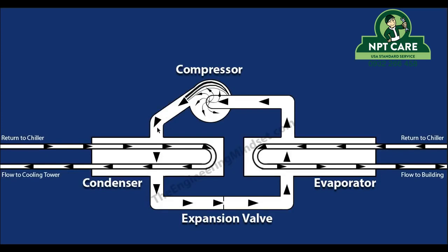The refrigerant comes in and condenses along the tube wall. It does not enter into the water. It just condenses on there and continues flowing through there, pushed by the static pressure until it hits the expansion valve. The expansion valve is just expanding that refrigerant, giving it a greater ability to pick up heat when it gets into the evaporator there.